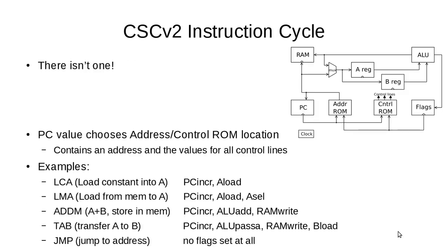Unfortunately, the Crazy Small CPU isn't traditional. In fact, because it's so minimal, it doesn't really have the concept of an instruction cycle. Effectively, if you know about microcode, then every instruction in the Crazy Small CPU is a micro instruction. So basically, every instruction is simply going to do one small task by sending out control lines to all of those different components and tell each and every one of those to do or not do something.